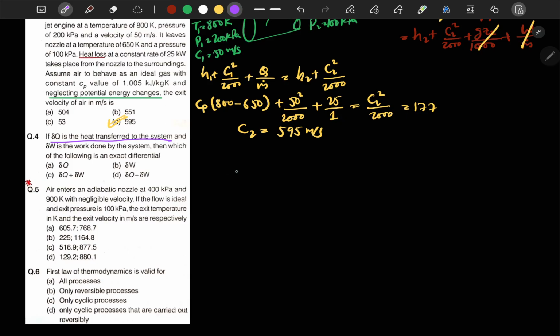We have discussed it in the last lecture, or last to last lecture, in the first law of thermodynamics, when we defined that energy is a property as a consequence of the first law. The first law of thermodynamics indicates delta Q is equal to dE plus delta W. From here we can write dE is equal to delta Q minus delta W. Since E is a property, delta Q minus delta W is also a property, so that is a point function.